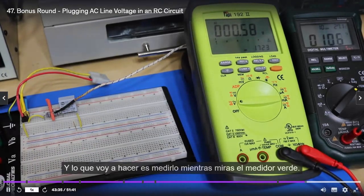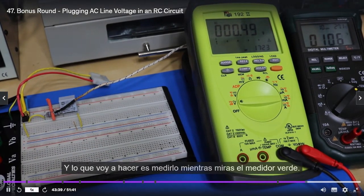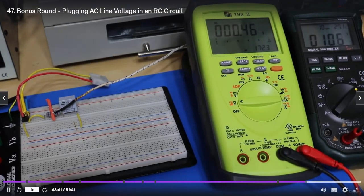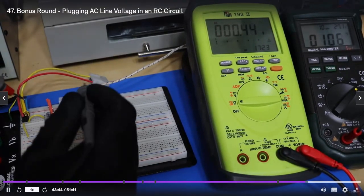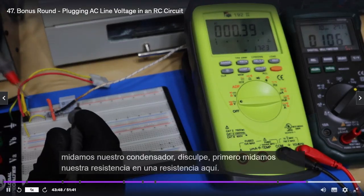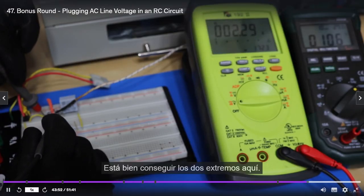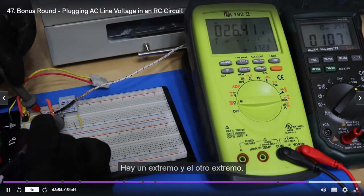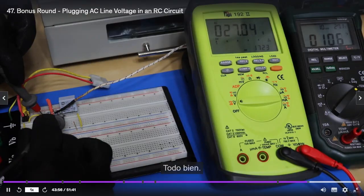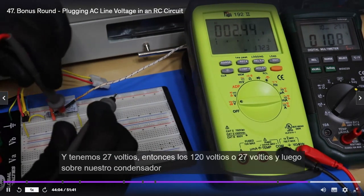Now I've got my meter here, and I'm going to measure this while you're looking at the green meter. Let's measure our capacitor. Excuse me, let's measure our resistor first. I'm getting both ends of it here. There's one end and there's the other end. And we've got 27 volts. So at 120 volts here, we got 27 volts. And then over our capacitor, what do we got?